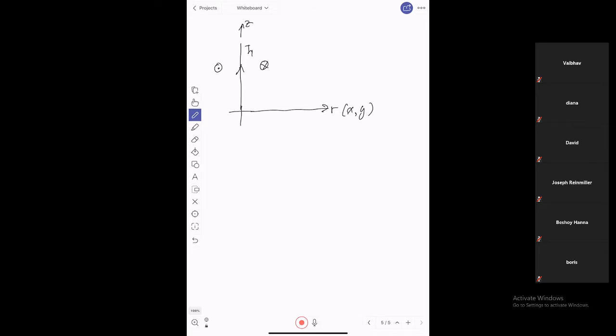The magnetic field here, of course, the further out you go, the weaker it gets, right? So the closest to the y axis is stronger, and this is weaker. It's going in here and going out from here, right? Any questions? As you go further out it gets weaker because it's 1 over R, right? The H due to the first wire has this magnitude. Of course, the direction is phi, going into this page over here and going out over here, right?